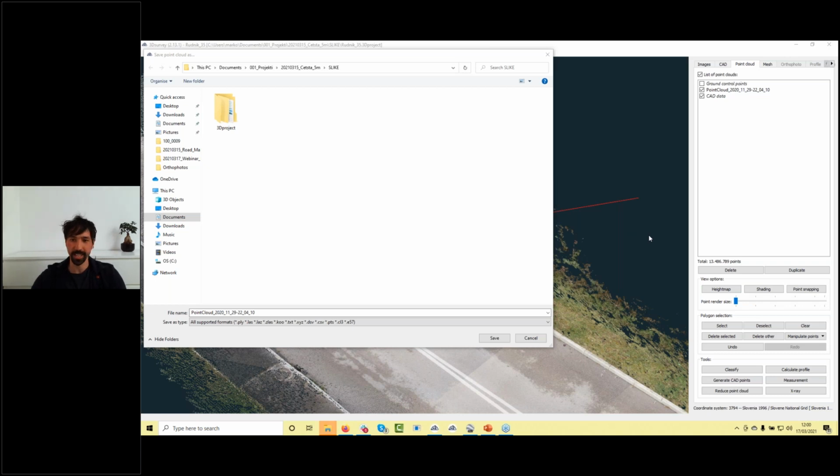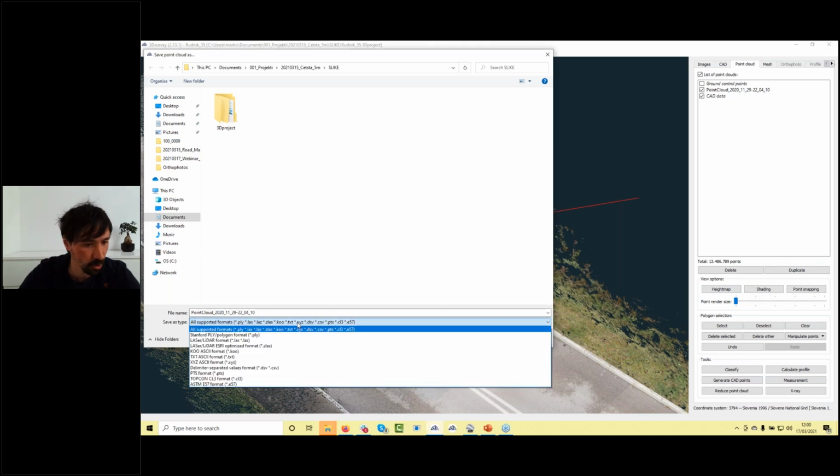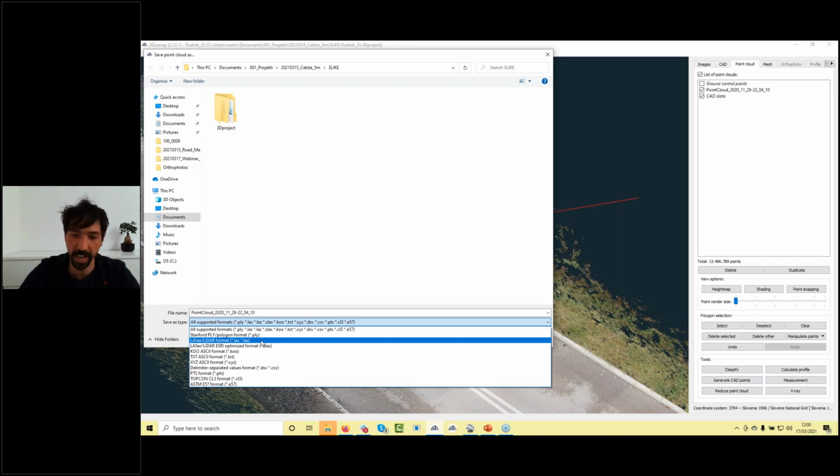Okay, we hit the 1 hour time. Let's just double check if there is maybe some additional question. Hello Marco, here is the correction: I mean colored laser file. Yes, of course, not a problem. Just go to point cloud, save as laser file, and that's it. You can also, as you probably know, import point cloud data from different sources.